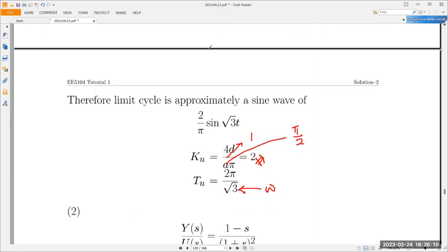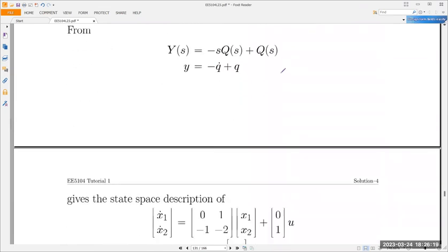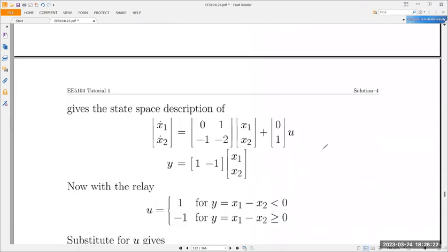So the first thing, we take this transfer function and convert it into a state space form. So I converted it into this state space form. Of course, the state space of the transfer function is not unique. Whatever state space you convert to, you just draw the x1, x2. That's fine. So this is just one example of a state space representation of the transfer function. We'll draw the x1, x2 of this.